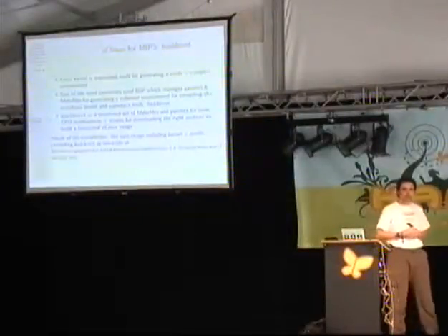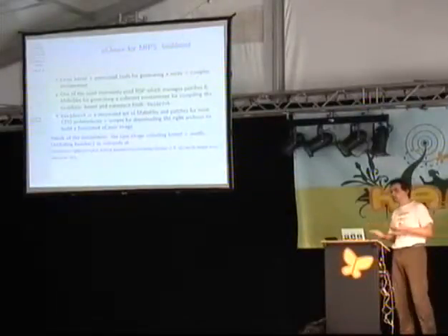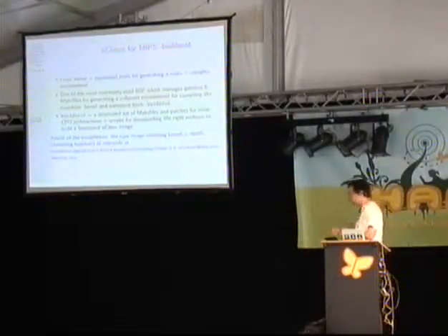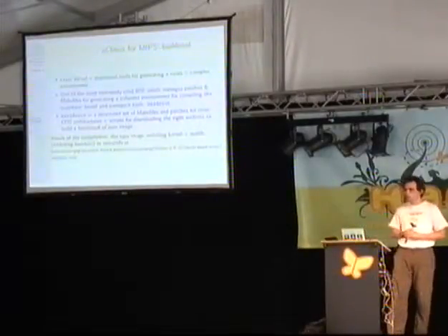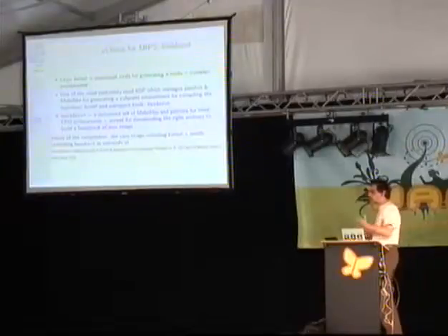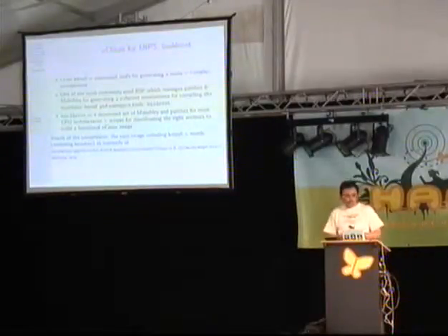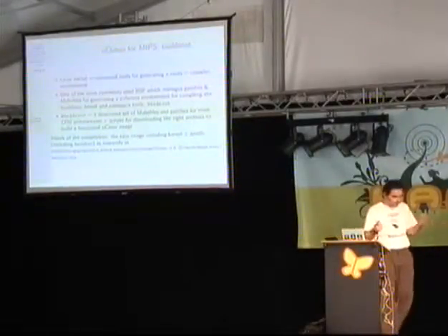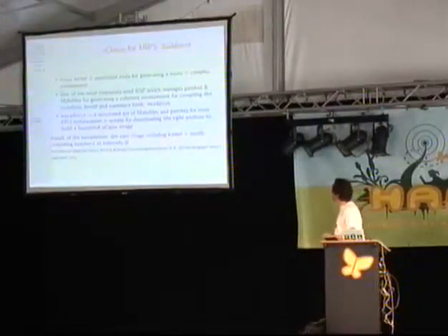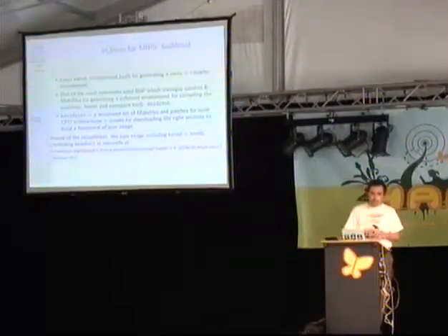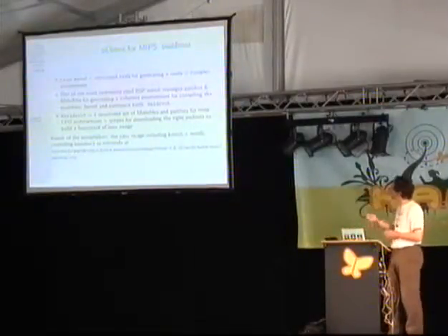And then I tell you that I enjoy working with GCC, Binutils, Newlib, but the fact is that now generating a full toolchain is becoming so complex that you need some kind of environment to help you with these tasks. One of these, yesterday we've seen in the OpenARM presentation, something like embedded Debian. That's too complex for me. I'm still familiar with my free tools, and I'm trying to learn how to use buildroot.